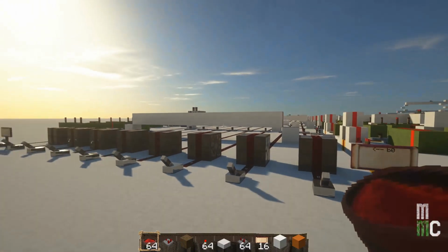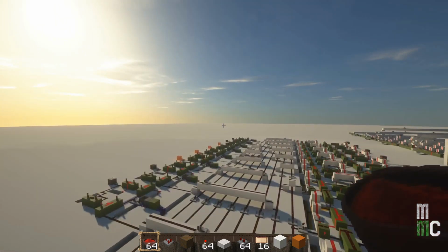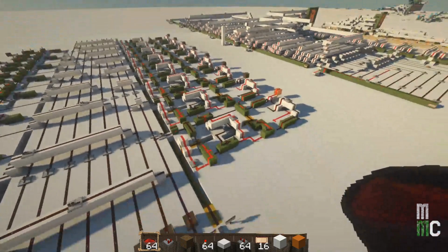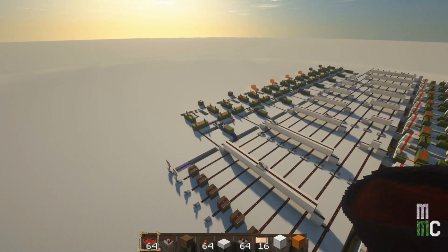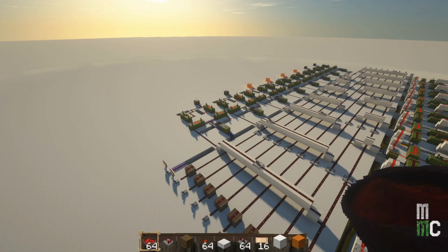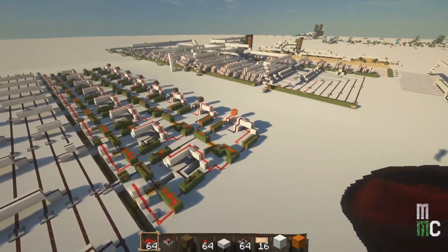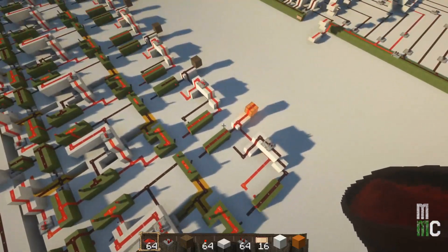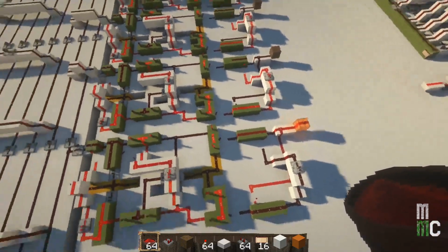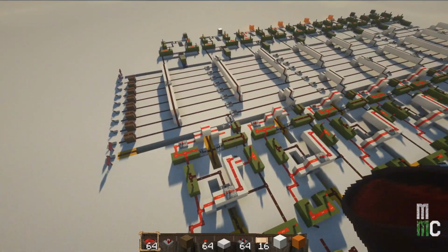So we are back at our 8-bit bus. We built our 2 registers. Here's our D-type flip-flop register, which is larger. Here's our simplified register, which is an SR latch with a monostable circuit attached to it for the enable line. But we're going to work over here today, and we're going to bring this particular connection from the output here all the way back to the bus, just like we did in Logisim.